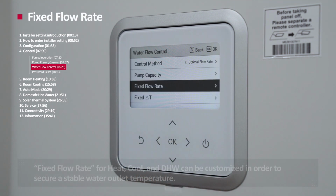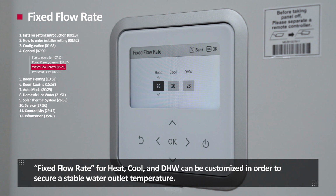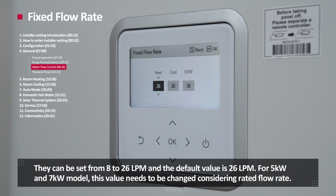Fixed flow rate. Fixed flow rate for heat, cool, and DHW can be customized in order to secure a stable water outlet temperature. They can be set from 8 to 26 LPM, and the default value is 26 LPM. For 5 kW and 7 kW models, this value needs to be changed considering the rated flow rate.